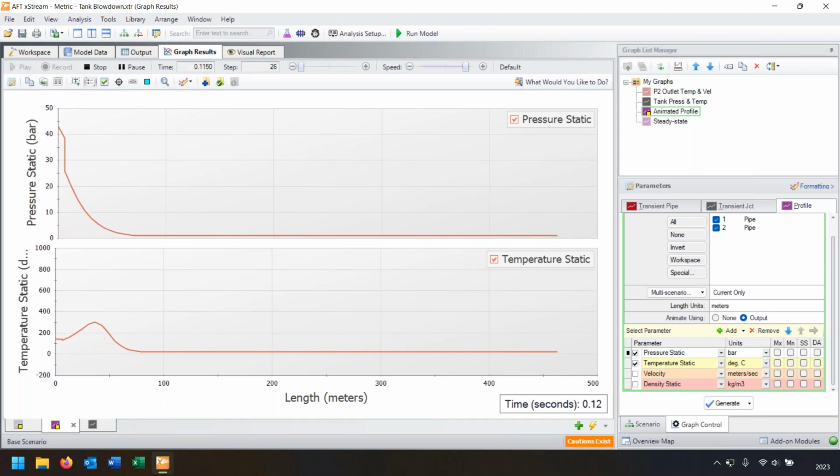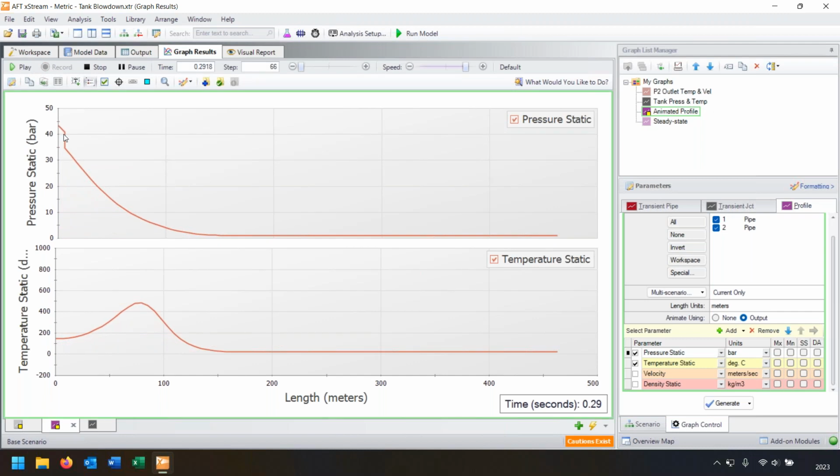And when we play our animation, originally we were looking at how that pressure was developing and how it was transmitting through the system. But we didn't really see that formal of a pressure wave. It's kind of implied here at this inflection point, where it starts sloping up. Here, if we're looking at temperature, it's much more dramatic. So as we suddenly compress all of the static fluid, or the stagnant fluid, I should say, in the second pipe, part of that goes to increasing the temperature of the fluid itself. So we see that increase in temperature.